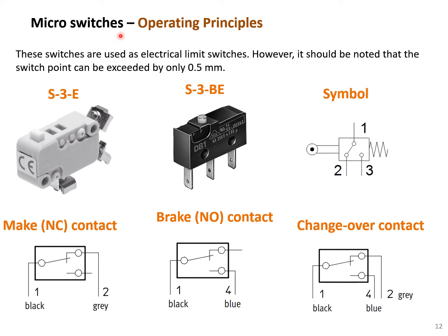Microswitches. So far we discussed optoelectrical switches and the proximity switches. But what about mechanical contact switches? We call them microswitches. These switches are used as electrical limit switches. However, it should be noted that the switch point can be exceeded by only 0.5 millimeter.